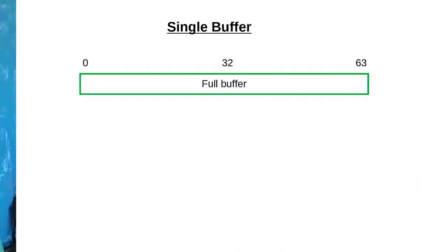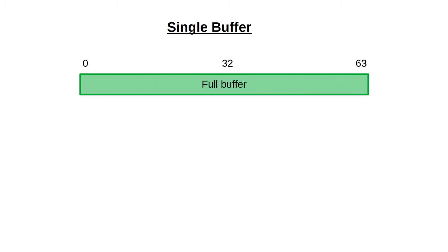But now we have the DMA working, but we want it to work in circular mode, not what they call normal or straight mode, and I'll explain why. Okay, so this is how it works. The basic DMA: you fill your buffer and you tell the DMA to start, and the DMA plays through to the end and stops, and it sends you an interrupt, at which point you have to refill the buffer and start the DMA off again, which is fine, but it means you need to be able to calculate a full buffer's worth of samples in one sample period.